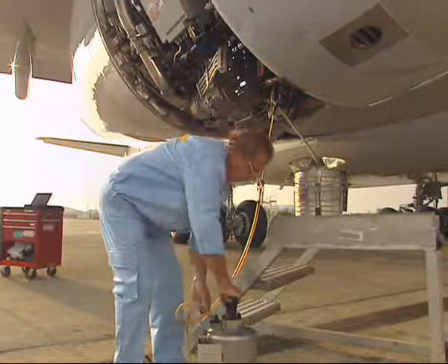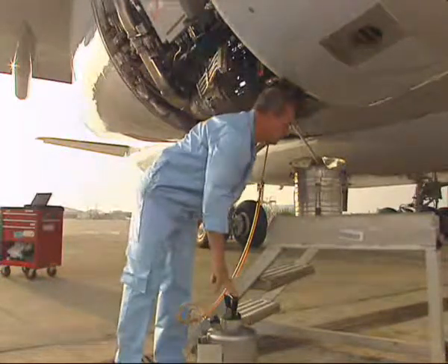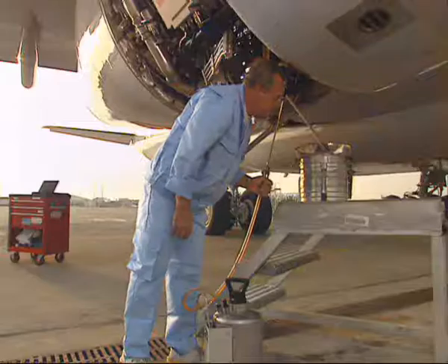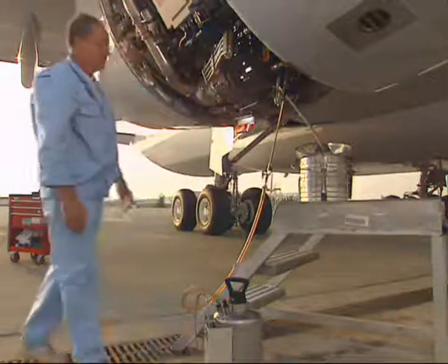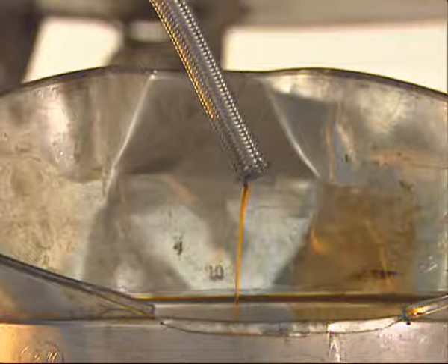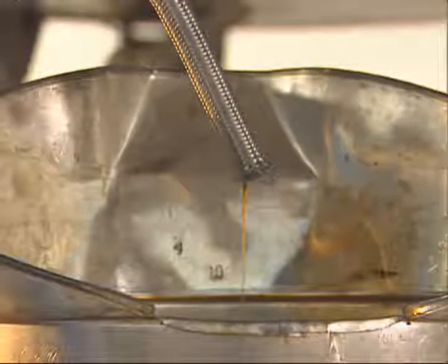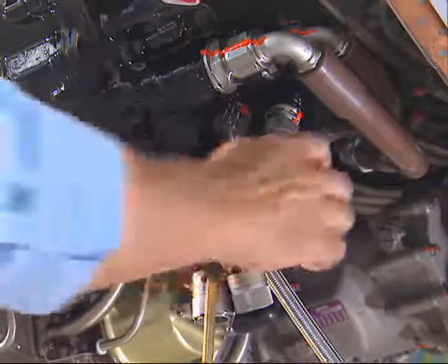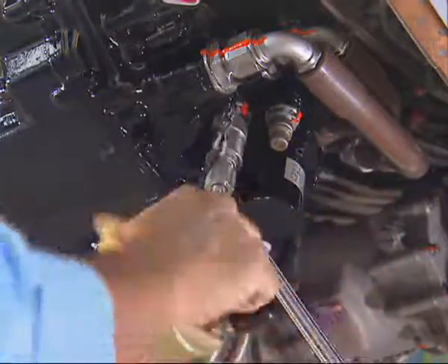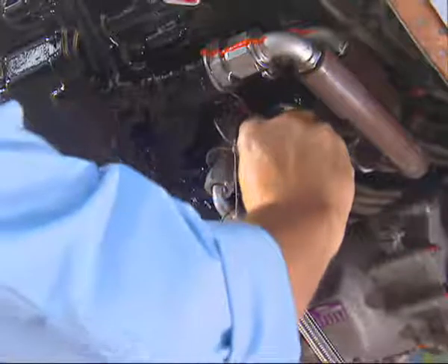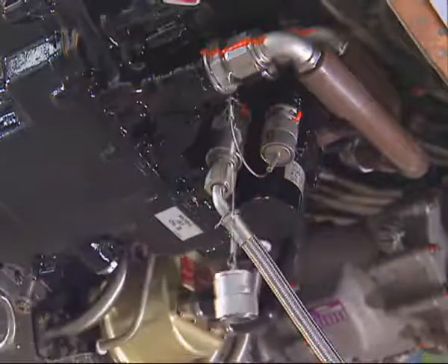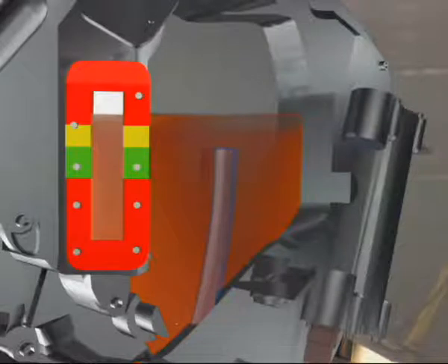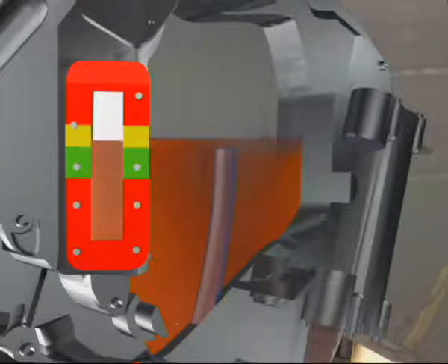Stop pumping when the quantity of oil collected at the overflow drain hose exceeds 1 liter or 1 quart of a US gallon. The oil will continue overflowing until the level has dropped down to the top of the overflow standpipe. While the oil is overflowing, remove the pressure fill hose. Install the dust cap on the pressure fill port. Once the oil level has reached the top of the overflow standpipe, the oil stabilizes at its optimum level at the top of the green band.